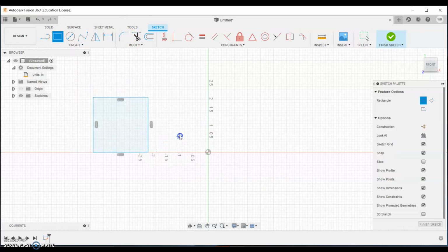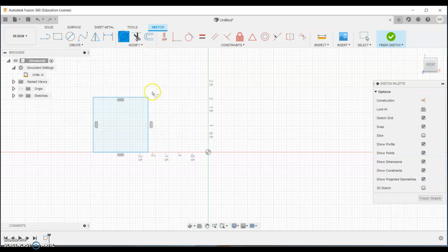All right, a fillet, we're going to get into that here in just a second. So here's my box. If I want to fillet it, I'll use the fillet tool. Basically this just allows me to create an arc, so that it's a curved edge instead of a pointed edge. Depending on how you change that, that's going to change everything. So the radius there would be 1.